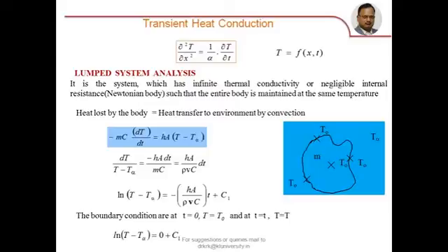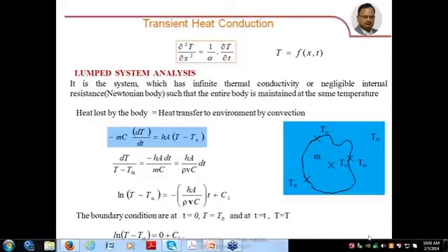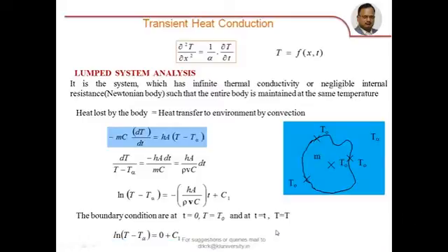These are three cases we will see in three parts. In addition, there are a few more cases where the convective heat transfer coefficient of the surroundings is infinite, or sinusoidal variation of the temperature. These are all different cases we assume to generate the boundary conditions. That is the purpose.